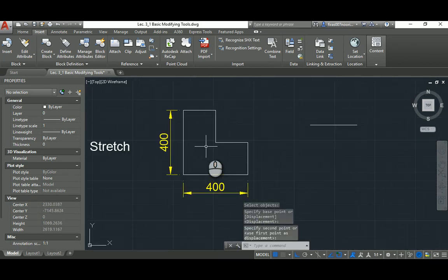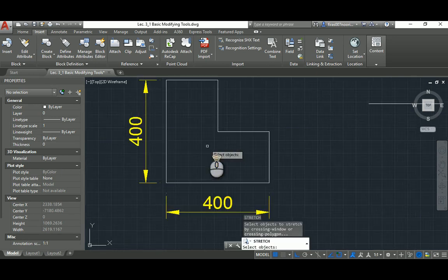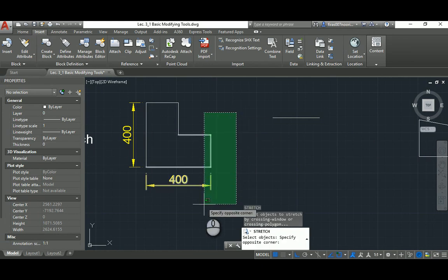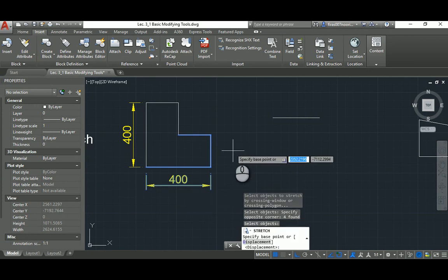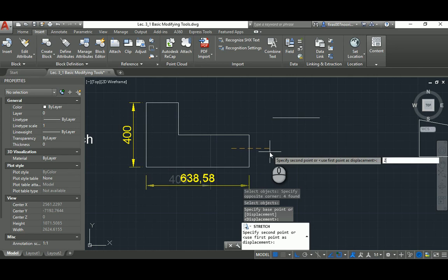Now how you get this interesting is when you work on a plan. So for a boundary, before we go on plan, let's select objects, select this. So technically this end, and the mid, so all this will increase in length. So this will move, those will extend. Same thing with this, I stretch this point so the dimension goes with me. Hit space to finish the selection, specify the base point, and then move your hand to the right with 200 and then space.